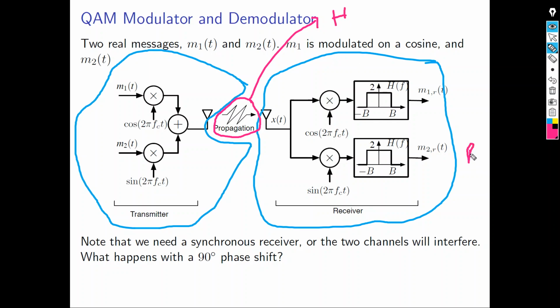So this is the receiver, your mobile phone, and this is the tower, let's say, and you are communicating by using QAM modulation. You multiply the first signal by cosine 2 pi fc, the second signal you multiply by sine 2 pi fc, and what happens then? You sum them on top of each other. You sum this signal with this signal to get another signal. Now you tell me, okay, we are summing them, putting them on top of each other. How come they don't interfere with each other? They don't cause any interference.